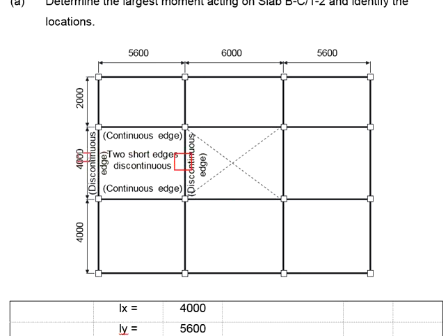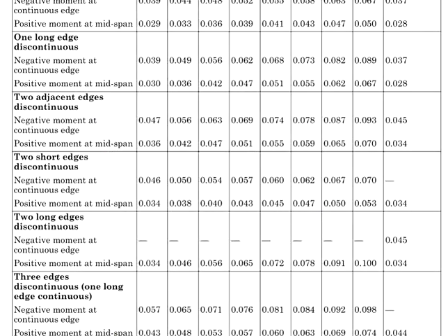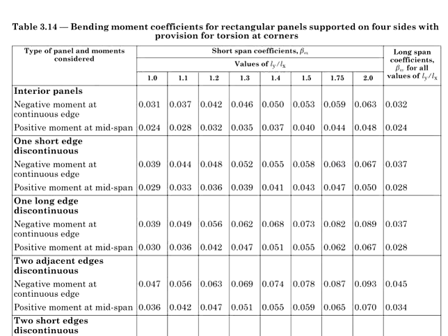0 moment here and 0 moment here. Identifying which span is which may be easy for this kind of slab. What if the slab that you are dealing with is something like this or something like this? Now you cannot use this dash to identify which coefficients are used for which conditions. And now you may find yourself lacking confidence, not sure where these coefficients are referring to.